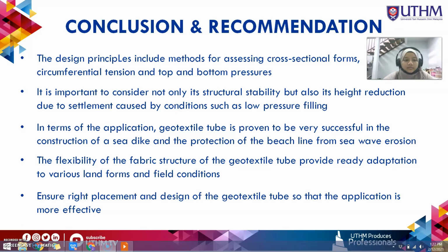In terms of application, the geotextile tube is proven to be very successful in the construction of sea dikes and the protection of the beach line from sea wave erosion. The flexibility of the fabric structure of the geotextile tube provides ready adaptation to various landforms and field conditions.